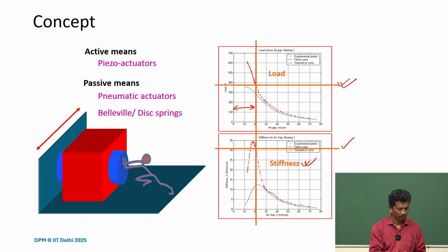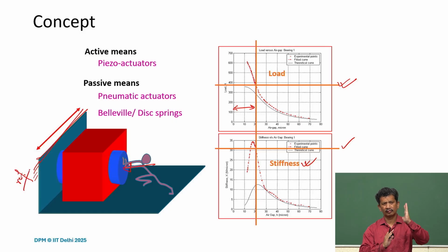So now you can imagine that it is pressed with this force, and then when it slides, this is the reference surface we are talking about. It can be flat and have very good straightness, and then it can follow. And even if the straightness is not there, if we are able to get the location, we know what the air gap is and what the deviation is, we can always compensate.